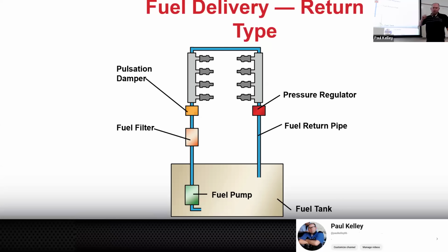So under wide open throttle, we can indicate, remember, if you go back to vacuum, we have a lot of vacuum at idle. At wide open throttle, we have basically zero vacuum gauge pressure. And so a lot of times when you have 0 PSI right here, it'll bump up your fuel pressure a bit. Part of the reason I've brought that up is two things. One, I've seen where people try to make their car higher performance by disconnecting the vacuum line and plugging it, and that will technically increase your fuel pressure, yes. Your computer is going to compensate for that and slow your injectors down a little bit, but that's true.